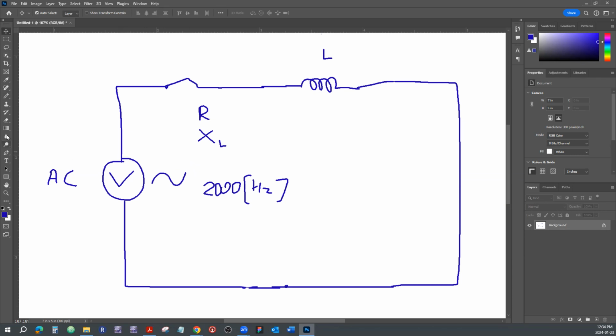The capacitor, on the other hand, is just the opposite. Capacitor loves change. To a pure DC, the capacitor acts like an open circuit. The coil acts as a short circuit. Now, let's substitute a capacitor here instead of a coil, with the letter C. All right, the switch is closed. We have an AC source going on.